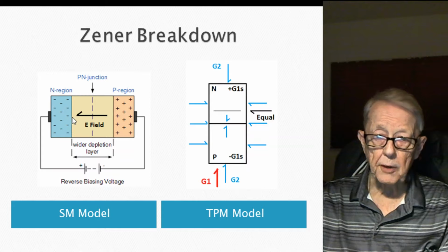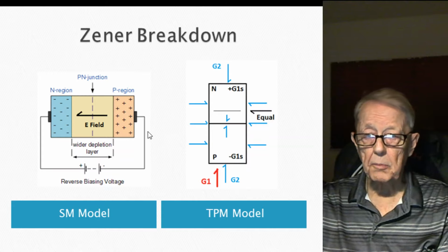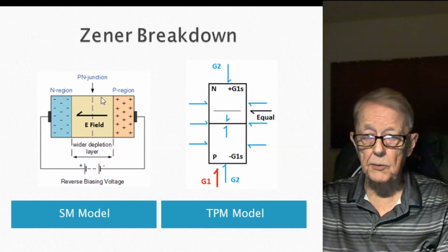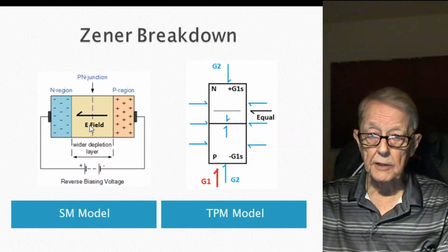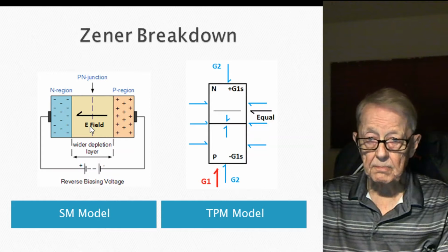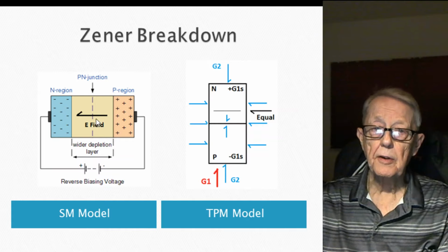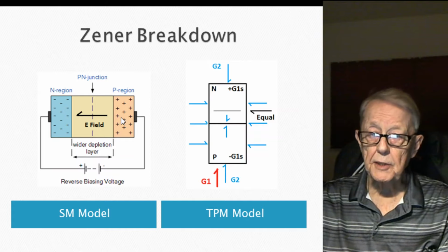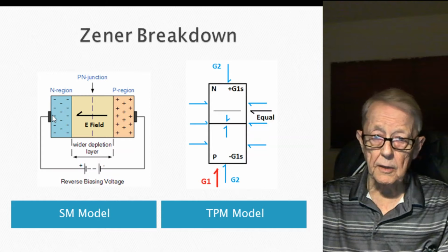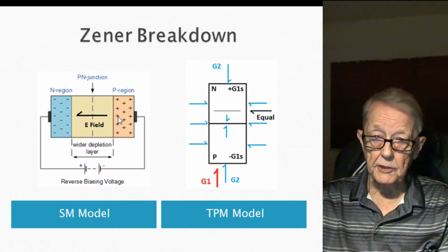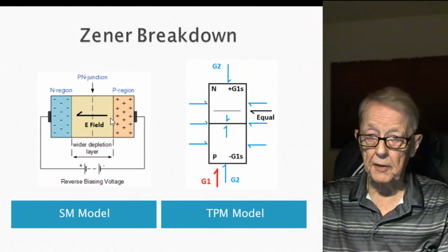The plus pulling the electrons this way, and the minus pulling the positive this way, creating this depletion region. This is in reverse, and it generates an electric field. Very simply, a positive particle to a negative particle, the field is always shown from the positive to the negative. I drew that arrow in myself in the word, showing that's the direction of the force.